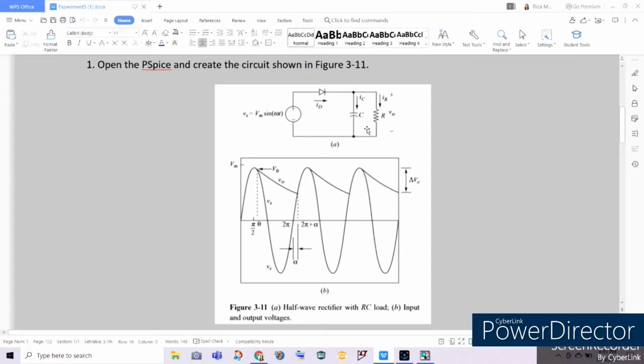So now, understanding rectifier circuits like this, for example, our half-wave rectifier with RC load, rectifier circuits aim to convert AC voltage to DC voltage as our output. So here, the capacitor serves as our limiter, or let's say it controls or regulates the variation of the voltage, and it is important in our rectifier, or it serves as our filter, and this resistor serves as our load.